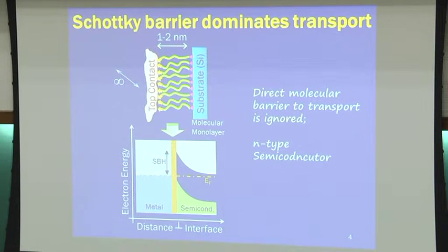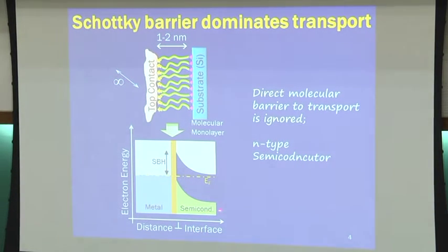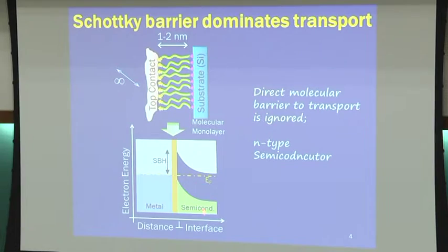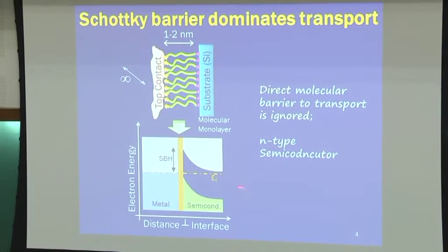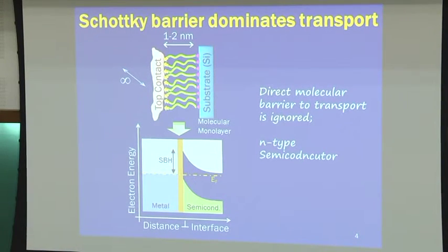And I will show you mostly these energy diagrams, which is like setting this interface upside down. The y-axis is the energy, the x-axis is the distance, and this would be the semiconductor with its forbidden energy gap. That's the metal, where the Fermi level is within the gap, and in between some interfacial modification. And remember, this is really nanometric, it's not to scale, so this interfacial layer is very narrow. And the critical parameter that I would argue changes is this band bending, the potential in the silicon. So my working assumption would be that this is the main barrier and not the barrier by the molecules.